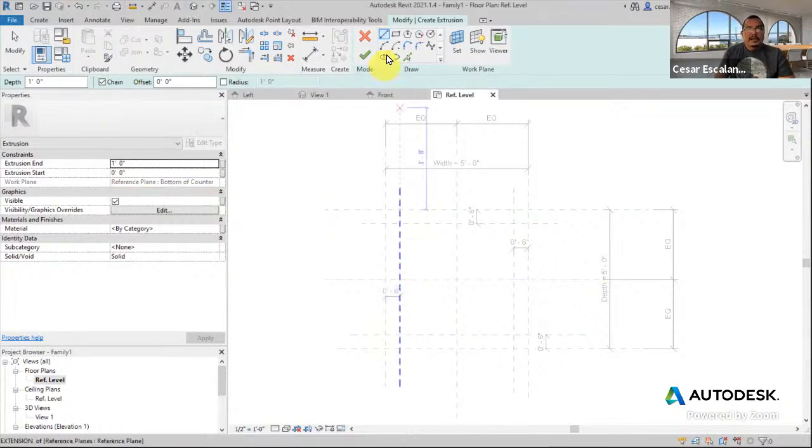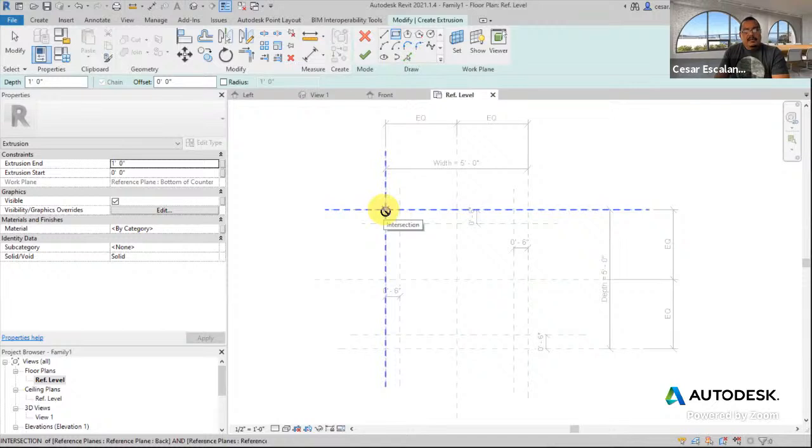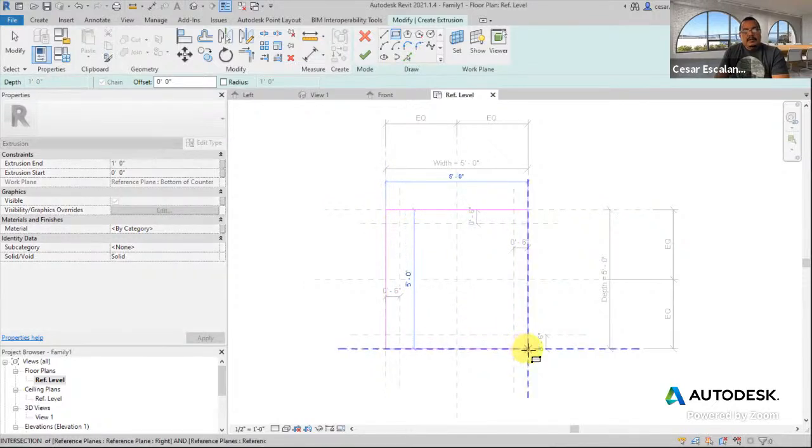And to make it easier, you can use a rectangle. That's the easiest way of creating a rectangular table. Pick the rectangle tool in the draw tools and snap from the upper left side to the lower right side. And notice these snaps. There is a snap action right now to the grid line. And you can see because there is an X here, and it says intersection.